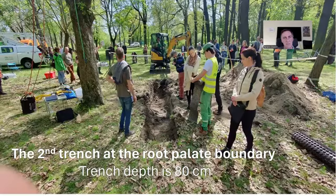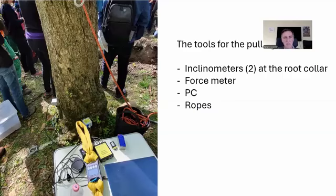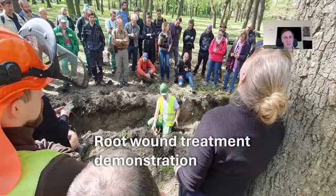I will show data later. The next trench was made 2 meters from the tree. Depth of the trench was 80 centimeters. And here you see the instruments we are using for the pulling test: the force meter, the central unit, the laptop. This battery powers all the units and the inclinometers. I mean, the force meter is powered by its own battery.